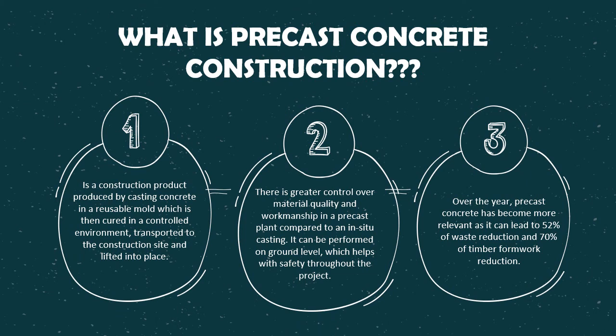Okay, firstly, what is precast concrete construction? As we all know, it is a construction product produced by casting the concrete in a reusable mold, which is then cured in a controlled environment in the manufacturing plant. After finishing, we can transport it to the construction site and lift it into place. There is also greater control over material quality and workmanship in a precast plant compared to in-situ casting. It can be performed at ground level, which helps with safety throughout the project.